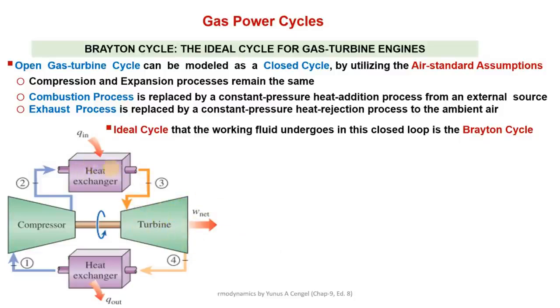gases. So in case of steam turbine, it was steam, the combustion gases were outside, but here in case of gas turbines, these turbine blades actually are rotating in those hot combustion gases which are burnt here. And here in case of gas turbines, the temperature at point 3 could be well above 1000 degrees Celsius, 1000 or 1500 degrees Celsius, right? So these gases are much hotter than those in the steam turbine. In the case of steam turbine, the maximum temperature is about 500 to 600 degrees Celsius.